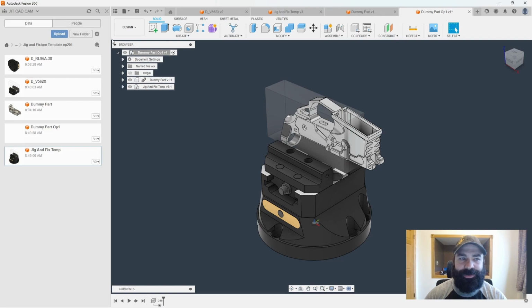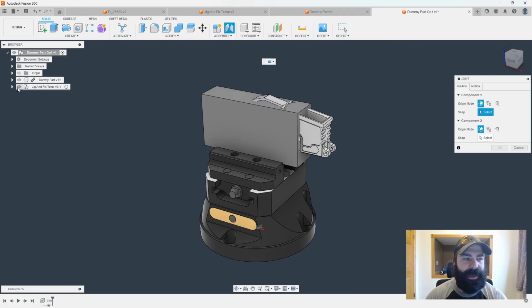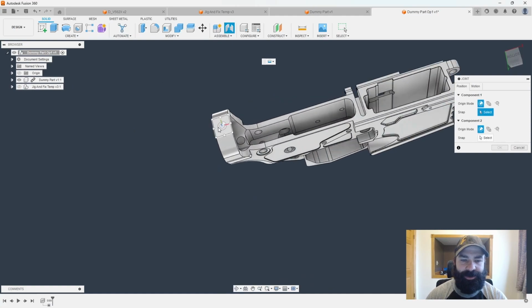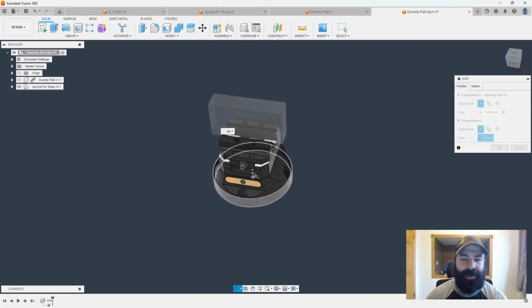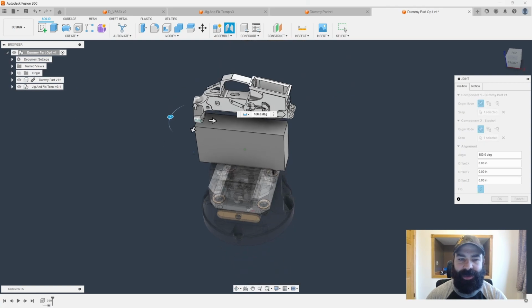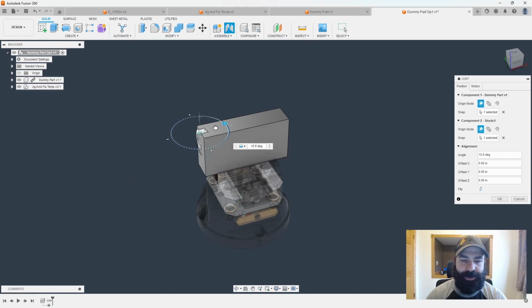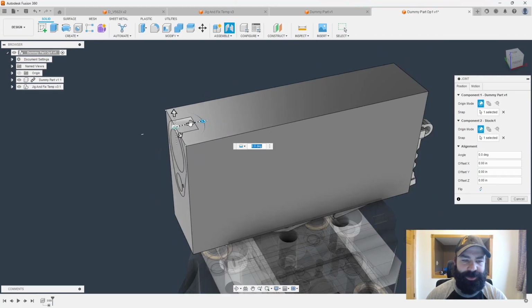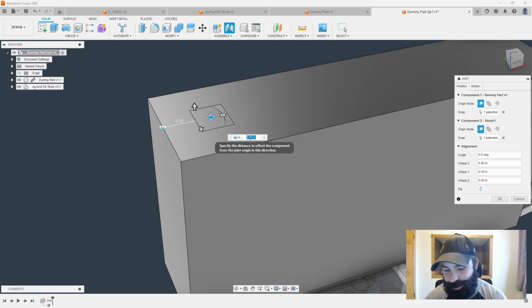But for most of you out there, you're probably going to guess this here is I'm going to now place my part on my stock where I roughly want it. And I'm going to do so with a joint. So let's go ahead and turn off our jig so we can grab an edge here. We did lock out that this part has a nice flat at the top. And I'm going to now rotate back around, and I'm going to place that over here on the back side of my stock. So now you can see my part's not turned on. I turn the visual back on so I can see where it's at. Again, we're upside down, so we're going to go ahead and flip, do a little bit of rotating. And then for those of you that do machining, you realize that you probably want to be in off the edge a little bit. That's a little overkill. So maybe we go 0.1.